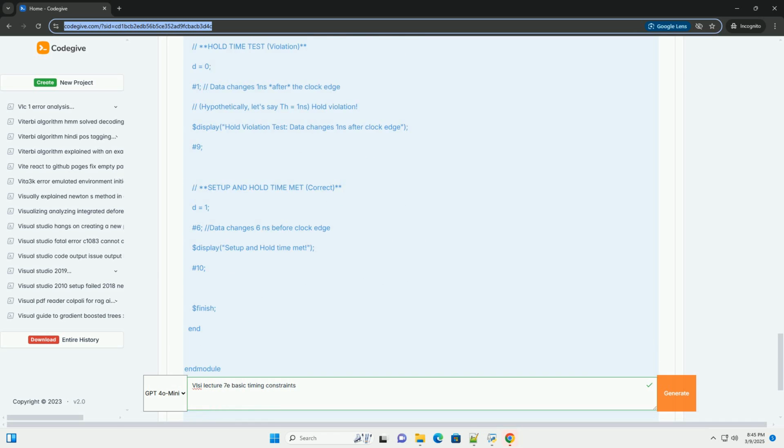How it works. 1. The first flip-flop, Stage 1, is the most likely to go metastable. 2. The second flip-flop, Stage 2, gives the output of the first flip-flop more time to settle to a stable value, 0 or 1, before it is sampled. 3. The probability of both flip-flops being metastable simultaneously is greatly reduced.